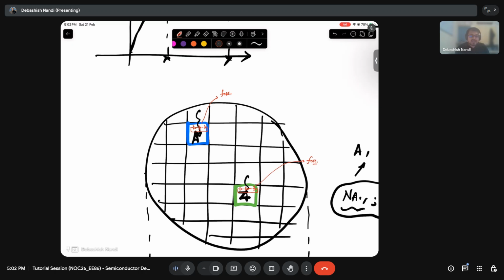By checking the deviation of FOSC from one place to another, they can get a fair idea about the quality of the fabrication process and whether any corrective measures are required. So for global process monitoring, ROs are very important.